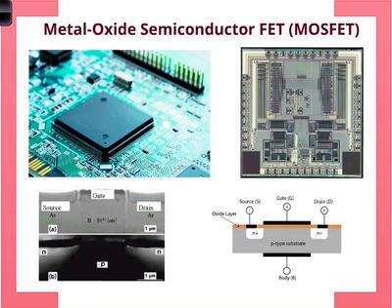But the reason this is most popular has to do with the fact that this has very clean signal characteristics, and it can be fabricated in an integrated fashion, in a silicon microfabrication process, without gold and things like that. So it's a fairly streamlined fabrication process. In any case, if you open up your motherboard, you see something like that. That's an integrated circuit.